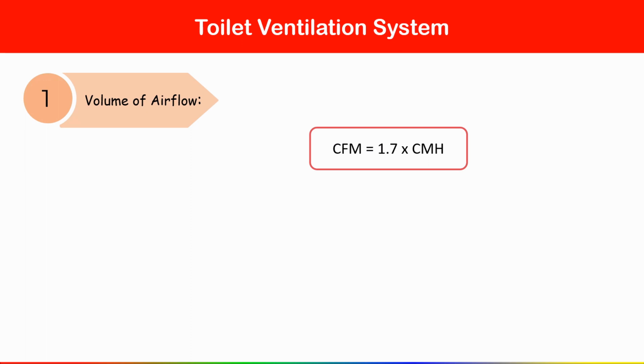So once you get the airflow rate value in cfm, you have to convert that cfm into cmh. Then only, with the help of the catalog, because in the catalog the airflow value is given in cmh only. That is why I am telling you to convert first of all. So you will get the model number of that fan, throw, noise level, everything they will provide you.